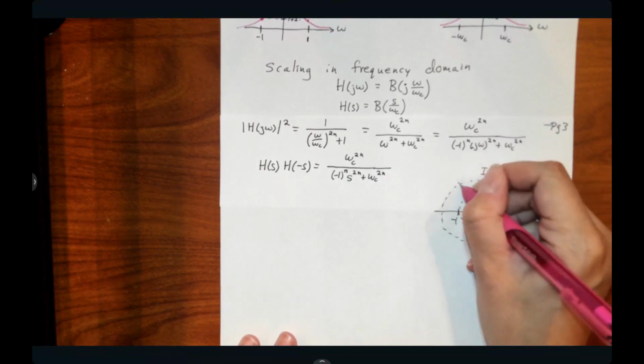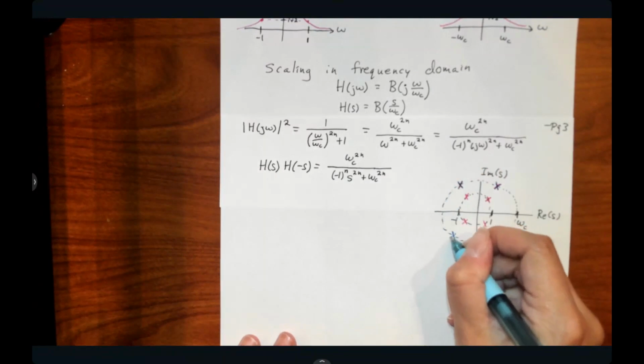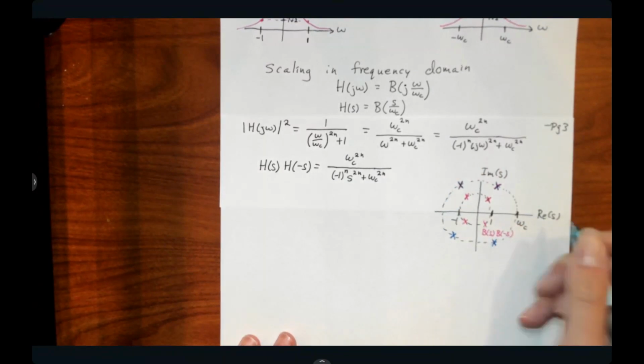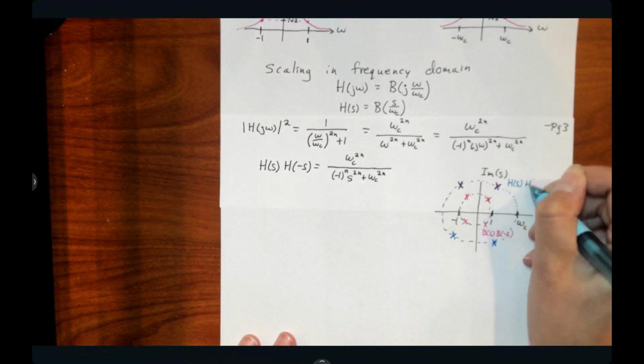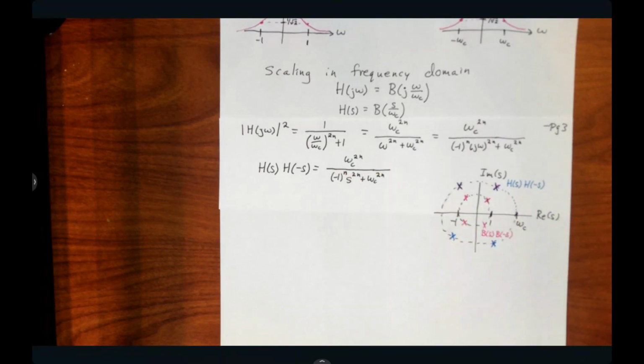They just get stretched out to this outside circle, like so. It's actually a pretty similar process. Even if you did the substitution beforehand and looked at this form to figure out the poles, the process would still be the same. In this case, since it's second order, you get 2 stable, 2 unstable, you just have a different magnitude that you're looking at.